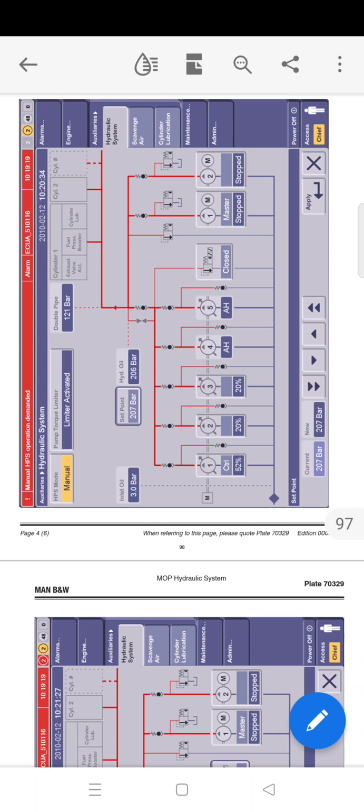So in case it is a 200 bar system, below 140 bar engine shutdown will happen, and if it is a 300 bar system, below 180 bar the engine will shut down. So both operating pressure and the shutdown pressure are engine dependent. The pressure set point is only relevant for the engine driven switch plate pumps, as the pressure of the engine startup pump is limited via mechanical adjustment pressure limiting valves. The startup pumps are automatically stopped at normal engine running.